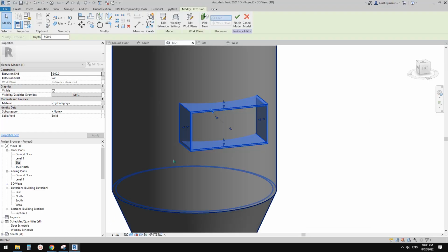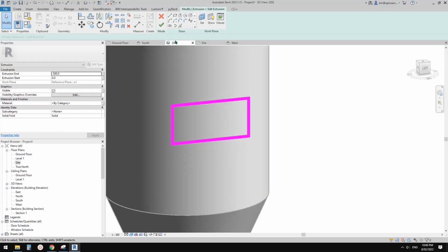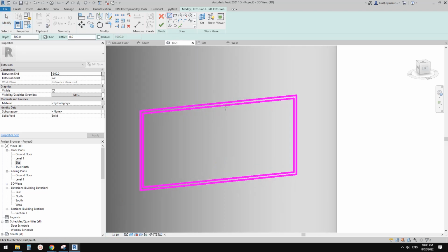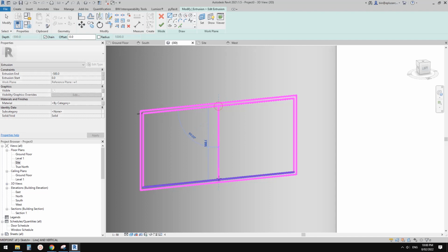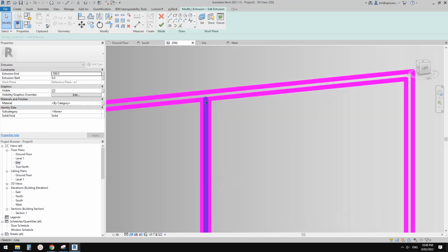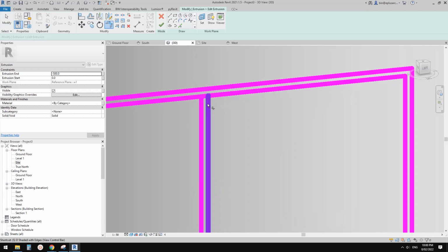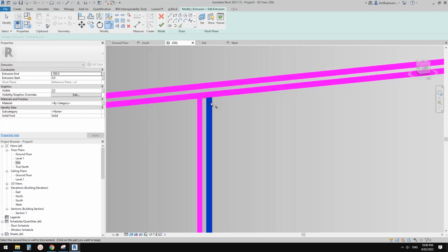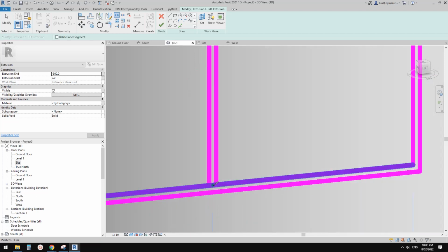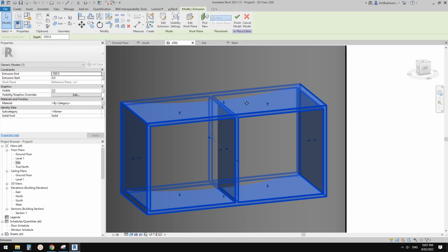Okay, so this is the frame, of course, and then we can add a vertical one. So edit extrusion. Let me change the scale as well. Line, middle, down. I'll copy this 10 to the left and 10 to the right. Delete the middle one. Split SL, trim TR, SL, split TR, trim, and this is the frame.